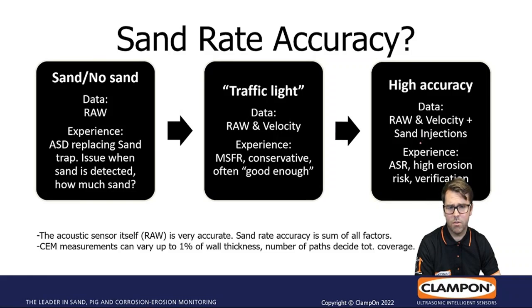This is needed if you are controlling your wells by acceptable sand rate, and you are up to the limit of what you are allowed to produce, and you want to see if you can produce on even higher rate, and maybe your system is too conservative. Then sand injection is a good idea.